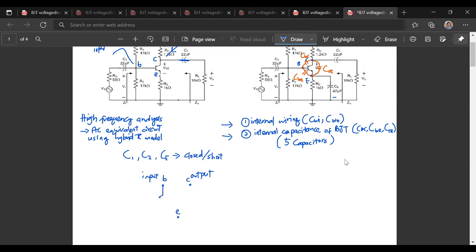Okay, so we draw the R pi, current. This is NPN, so the base is P type, the emitter is N type, so V pi positive is at the base, the emitter is negative, and the arrow for current is from C to E.